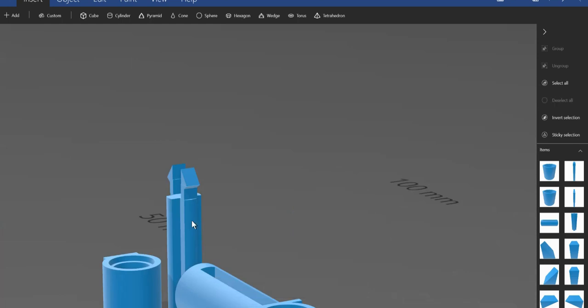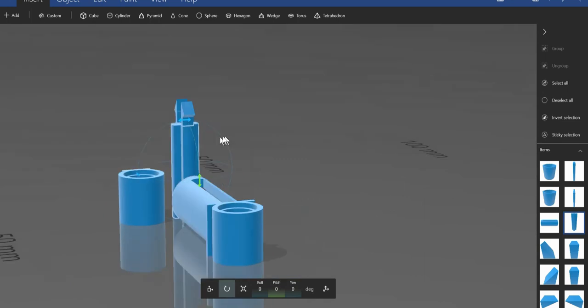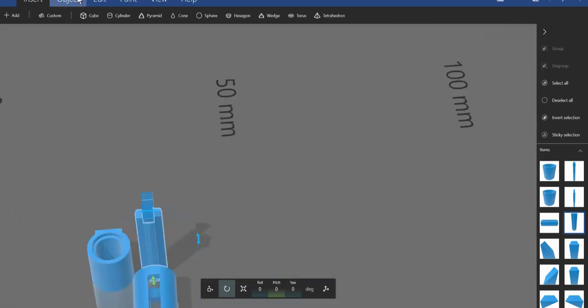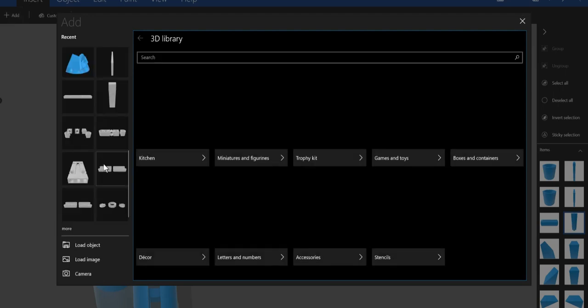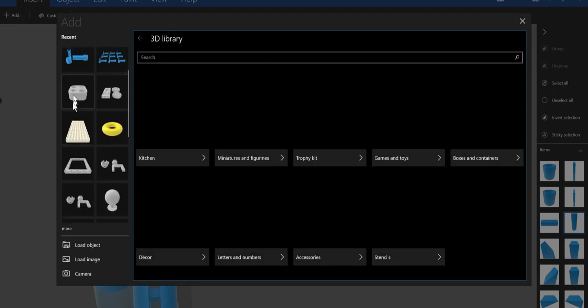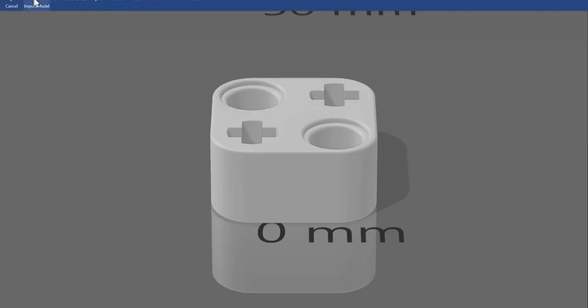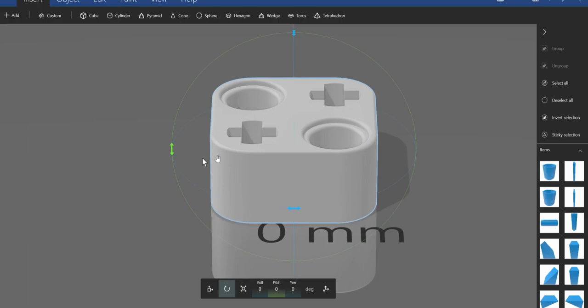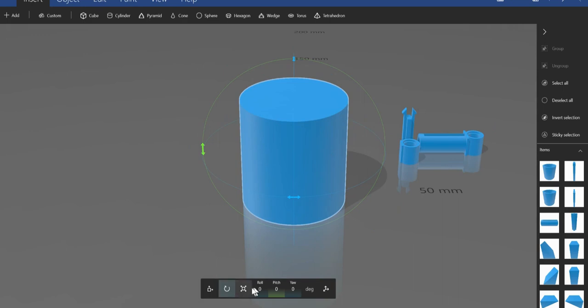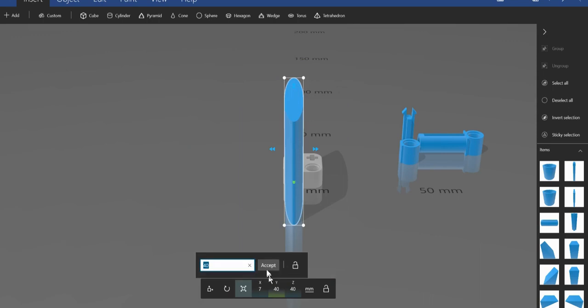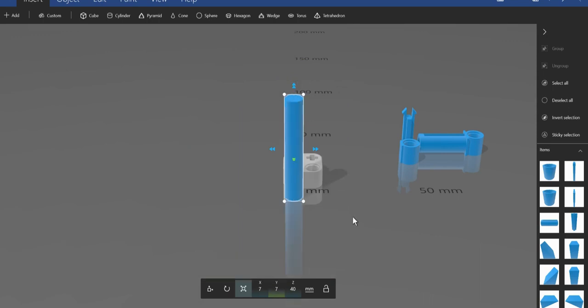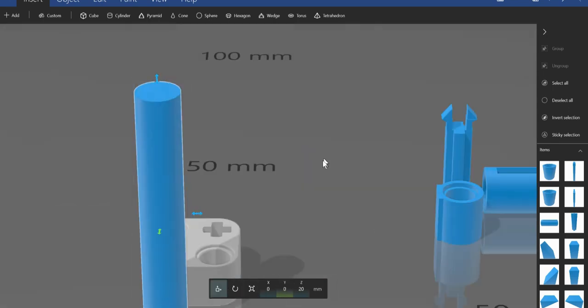This axle, how you could get this axle, basically what I did is I took the object that I found on Thingiverse, aka this weird square piece. This one. And then you see how it has axle holes? Basically, you take those axle holes, you put a cylinder or something, and then you make it 8 by 8 or 7 by 7 because I need it to be a little smaller. And then you just align it with the axle holes, and then you subtract it.